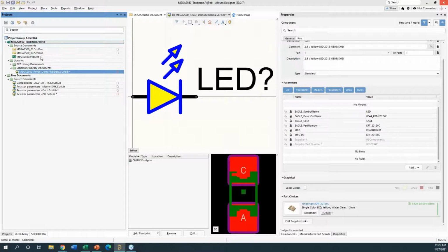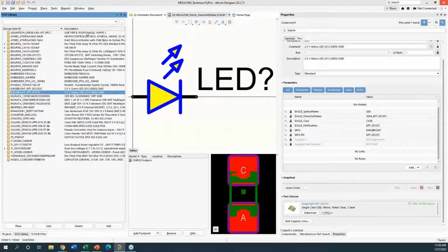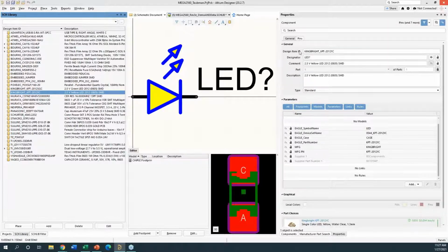So we were able to extract out the library, and this is the library that you're looking at right now. As a part of that assignment, I took all the parameters that were already existing in Eagle, and I put the prefix Eagle in front of them so that at least they had a shot at finding the part that was associated to it. They had some requirements in regards to how the name was supposed to be developed, and the description and comment could come from DigiKey.